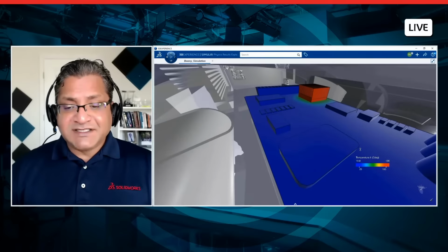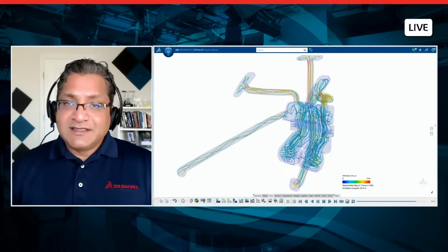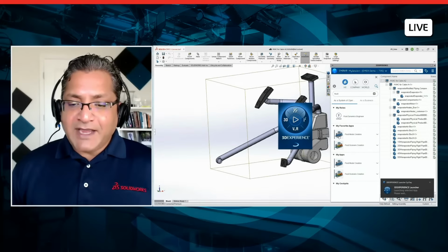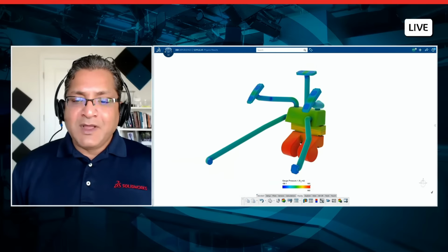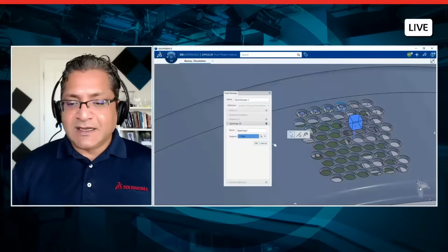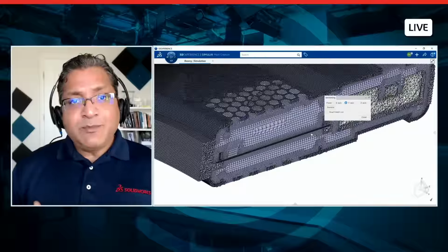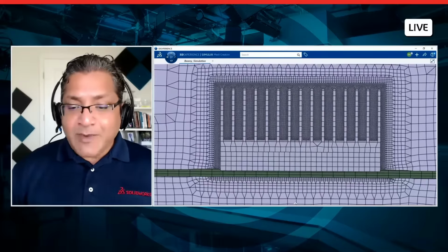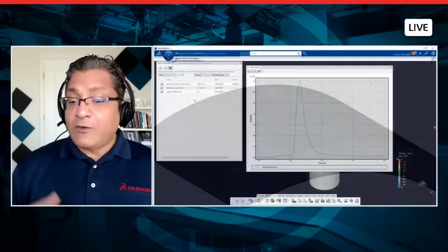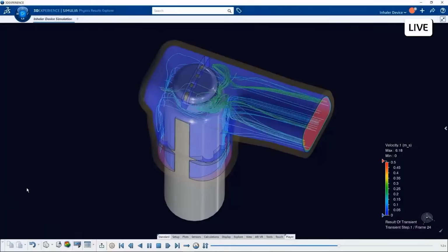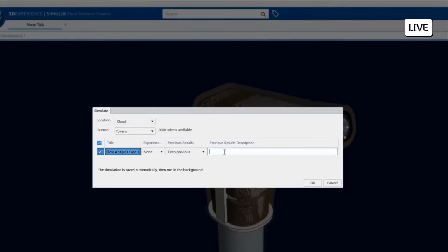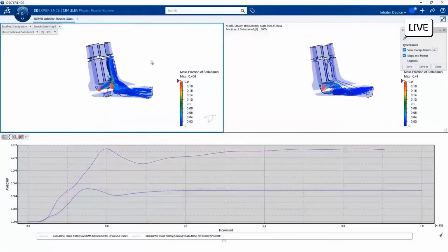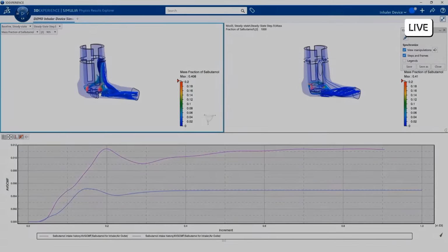In terms of physics capabilities, both tools offer similar capabilities, but the CFD on the 3DEXPERIENCE platform actually does a lot more in terms of being able to do HVAC analysis on large systems. And it also brings superior technology, like, for example, boundary layer meshing and advanced turbulence models, a rigid body motion solver, and even multi-species analysis, like this medical inhaler example that you're seeing here.